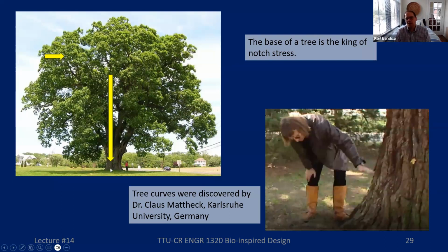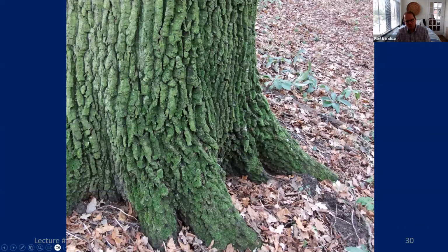And so people started looking at this, and this is one of the people who came up with the idea to understand why trees are so strong. If we zoom in a little bit, we can say, well, this is just a quarter circle, just another fillet like we had before. But if we do that, it's not really the case. It comes out quite far. This is a lot slimmer than a quarter fillet would be, which is good because it means less material.